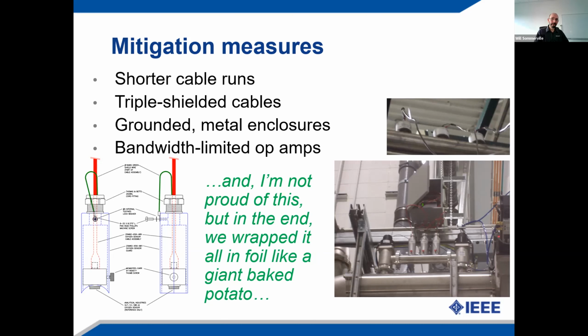We got bandwidth limited op amps that would not respond to the 13.56 and harmonics of radio frequency power that's running through the air. But I got to tell you though, after all that engineering, and we did engineer the heck out of this, we machined all this and precision fitted everything and bought special cables and everything. The thing that really saved the day, at the end of the day, and I'm not proud of this, we wrapped everything in foil like a giant baked potato.